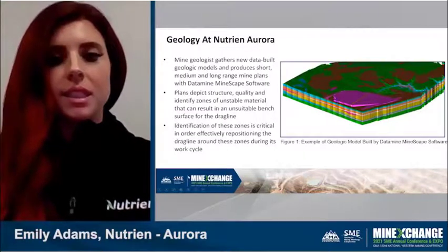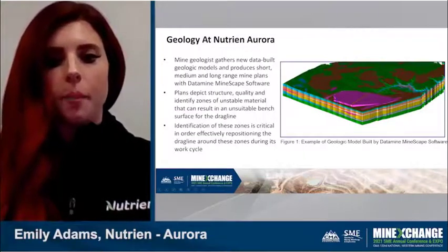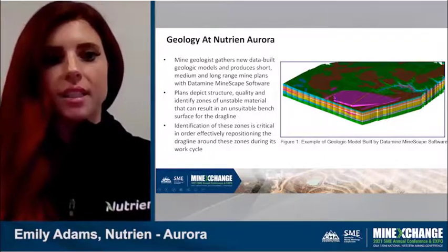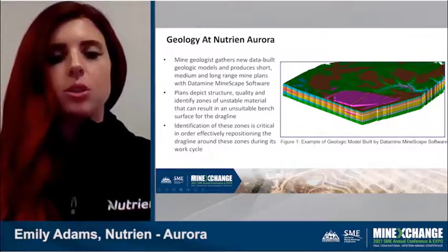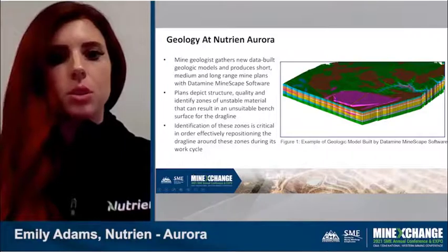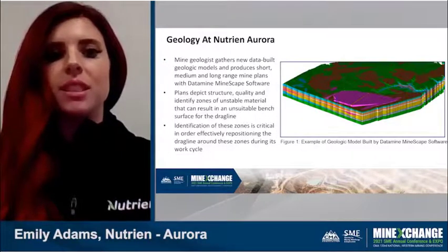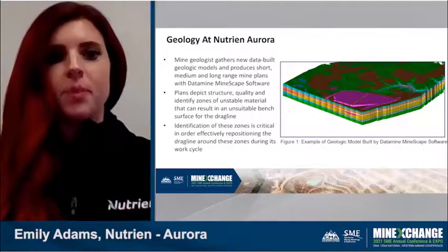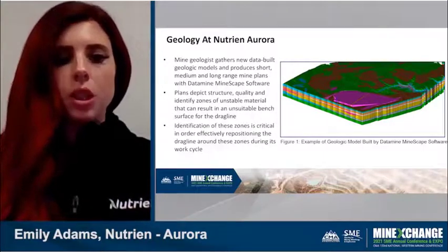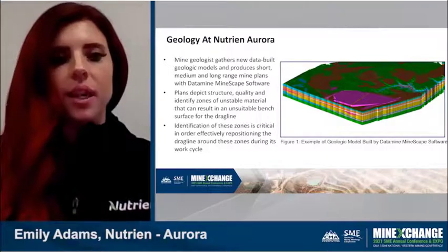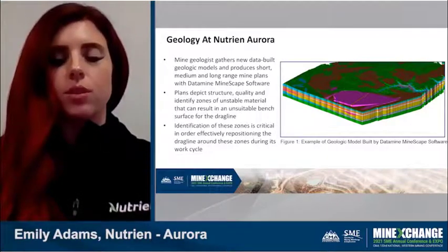Diving in a little bit deeper to the geology and what encompasses the role of the geologist at the site, I work to gather new data, build geologic models, and produce short, medium, and long-range mine plans. In doing so, I use the Datamine MineScape software. These plans will depict structure and quality. Additionally, we identify zones that are unstable material that can result in an unsuitable bench for the surface of the dragline.